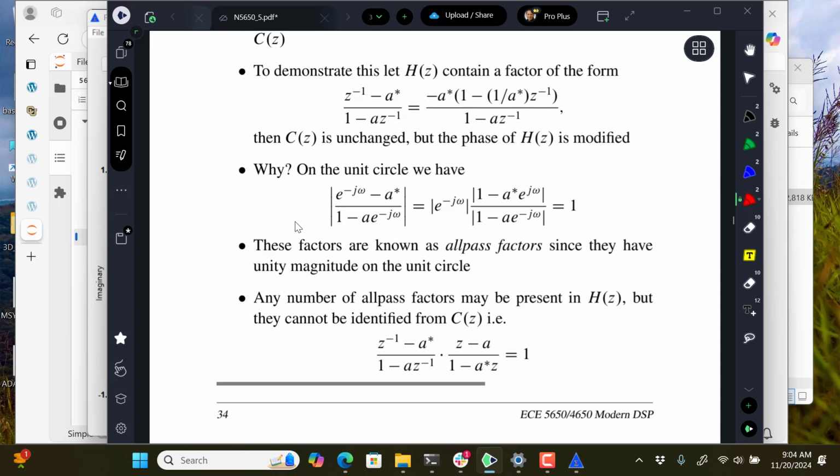So that would take more time to get to me because it's a longer path, and there'd be more path loss because there's 1 over distance squared path loss, the divergence of the rays and of the wave. But in cellular, with obstacles and things, the shorter path might be the weaker path, and the stronger path might be the longer path. And that will create a situation of a zero, and I'll show that here in a little bit, outside the unit circle. So it becomes a non-minimum phase mobile radio channel.